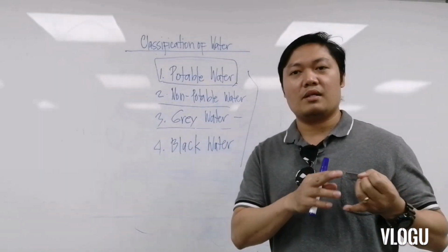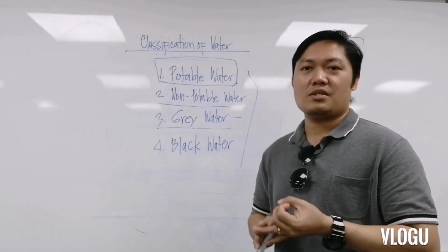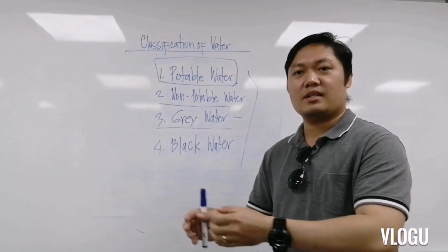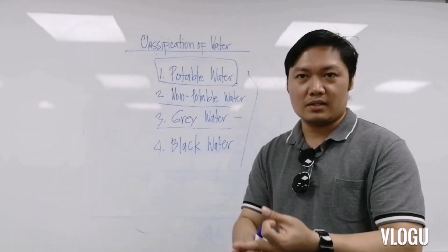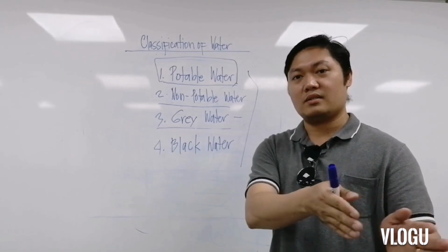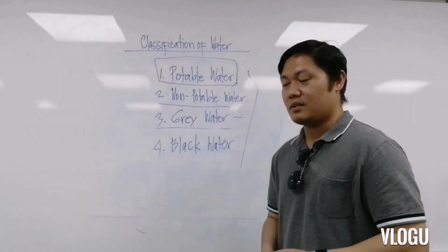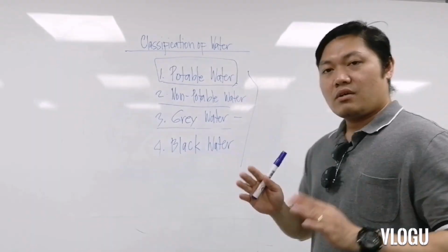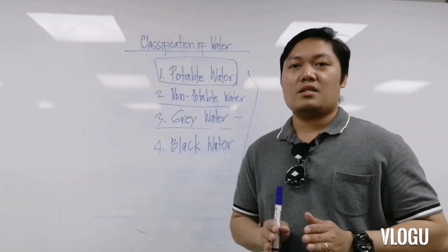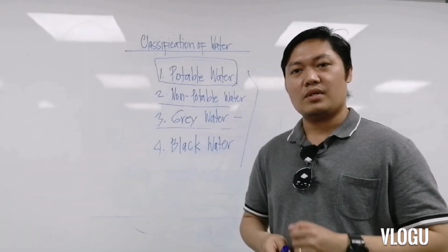And lastly, we need the necessary work permits before you execute on site. Let's say, for example, we have the environmental permits, the excavation permit, safety permit on site, hot work permit, electrical works permit if required, cold work permit on a daily basis, and so on. It depends on project requirements. After you complete all the necessary documentation and obtain all the approvals, you are now ready to execute the work on site.